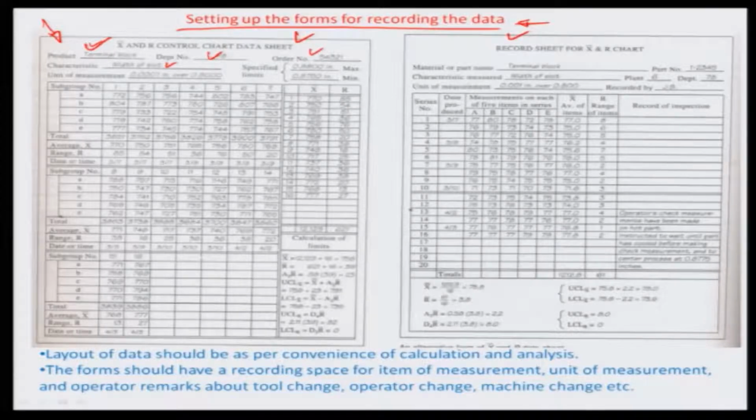Okay, they have given a unit of measurement which says that it is 0.0001 inches over 0.8000 inches. That means typically what you are doing is that you have made the same coded variable analysis. The values that you can see here are reported as 0.8 plus 0.0001 times the value that is in question. So basically this represents 0.8772, this 0.8756, this also again 0.8756, something like that.